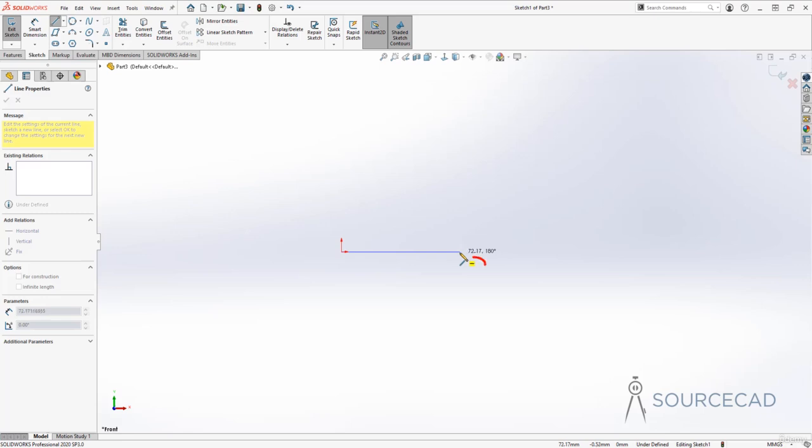Another thing is this yellow box with this line icon. Now that's a constraint. So in this case, it is applying the horizontal constraint on this line, which means if I make this line now, if I click here, I'll end up with a line that will remain horizontal, because as soon as I clicked, now you can see that we have that horizontal constraint added right here.